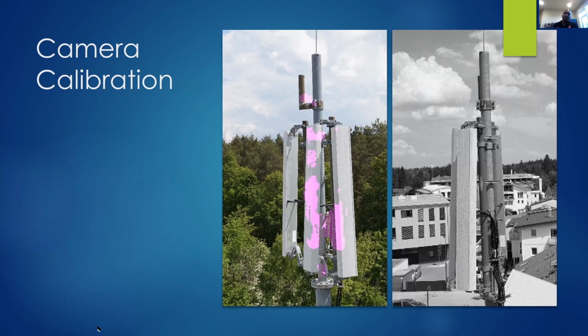And so one of the benefits of drones is they can do inspections for antennas, but generally you have some mixture of sensors, where you have your camera that you're using to take pictures, but then you may also need some type of sonar, and in our case, a RealSense camera that's giving us our depth. And so I did some work where we were taking the RealSense depth data and annotating the color picture data.